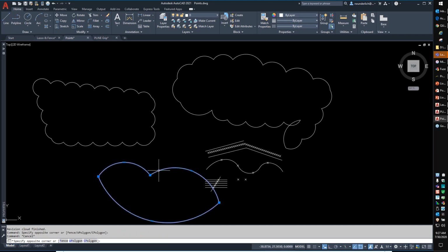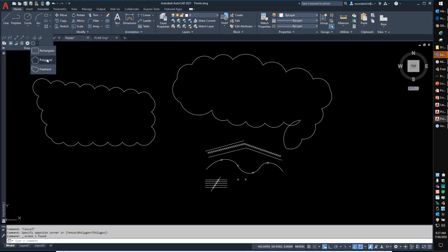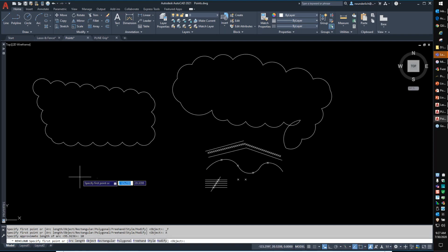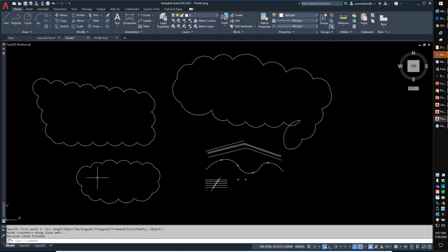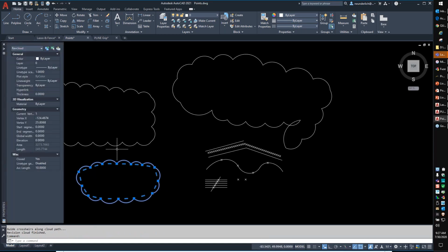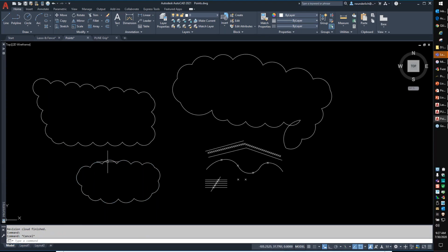There's some arc length variables in here. There's an arc min and an arc max that we need to go through and actually modify. And I'm trying to remember where that is. There's an arc length that is set with the revision clouds here. Let's see. Yep. Maximum arc length is 127, minimum arc length is 63. So this is where we want to change the arc length, and we want to change that to just 10. Now, if I'm drawing a freehand, you will see here that it tries to accomplish that, and it will actually make those changes. There is a place in the settings where you can set arc length min and arc length max so that that arc length will never change.